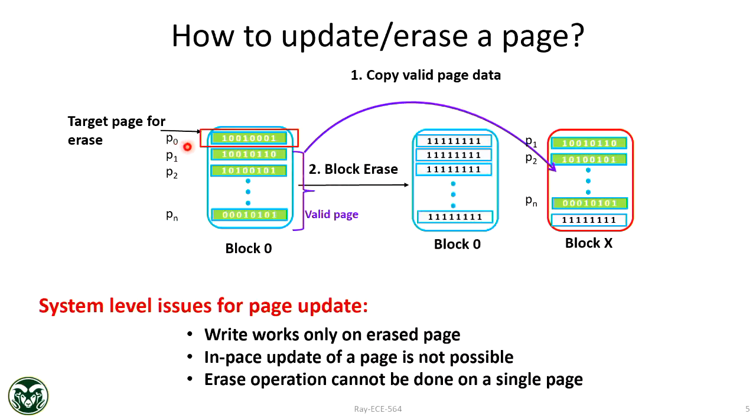So to erase one page, you have to erase all the pages. That's the only command you have for erasing. And then you can update this page and write on the new location. But all the valid pages have to be transferred. So that's a hefty operation, a hefty overhead.